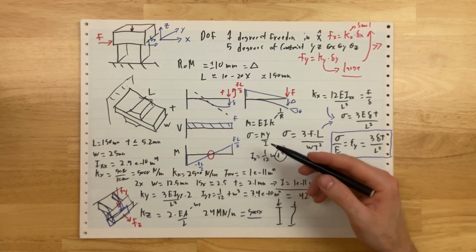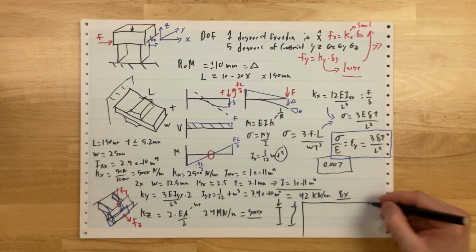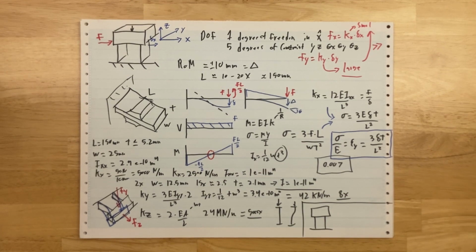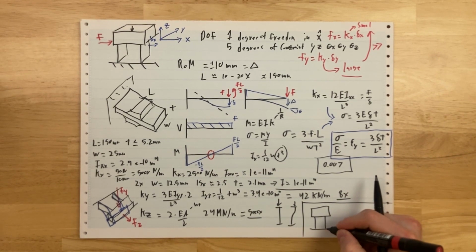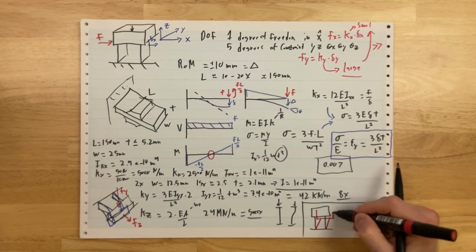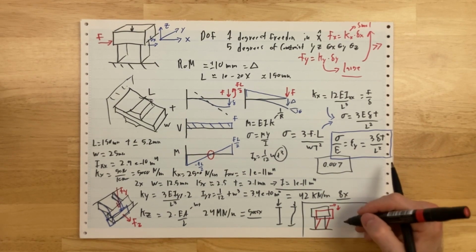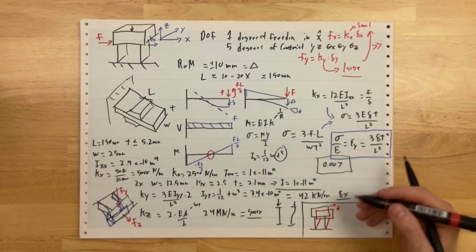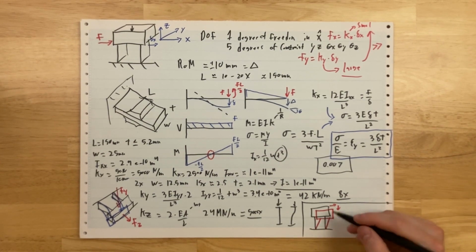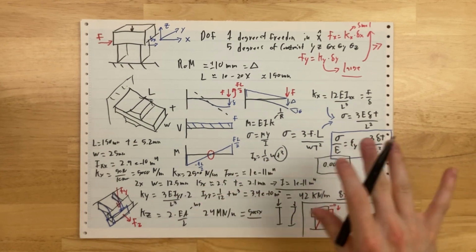There's also some pretty severe geometry nonlinearities here, or rather parasitic motions. I'm running out of space, but when you take this and you move it, essentially, if you squint really hard, they kind of look like pivots. These beams are just rotating. And you'll get this forward motion. You also get a parasitic lowering called foreshortening. Foreshortening is like foreshadowing, but not for tall people. And that is actually an issue. If you have a precision system and you think it's moving in a linear direction, but it's actually moving on this shallow arc, that's a problem.